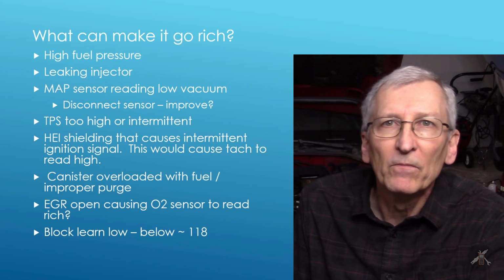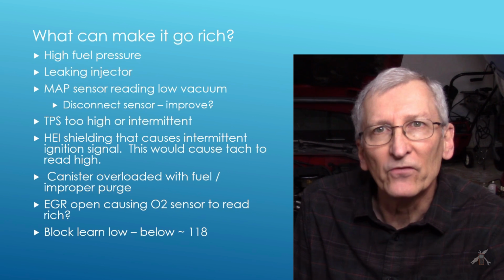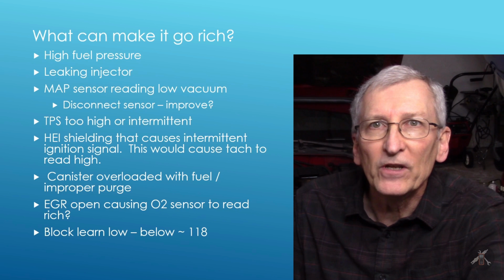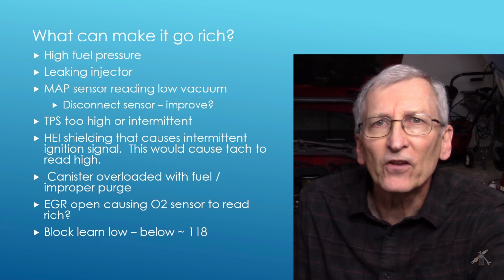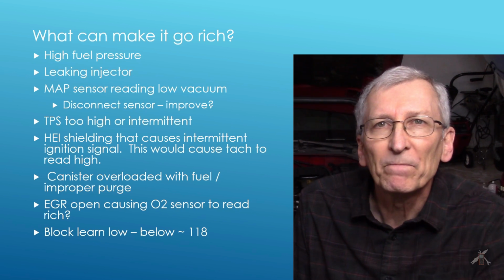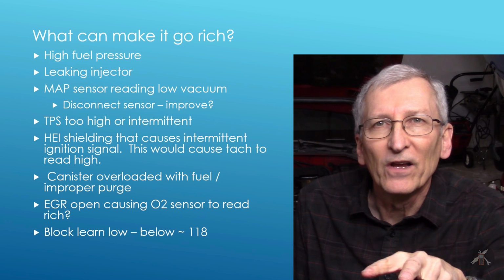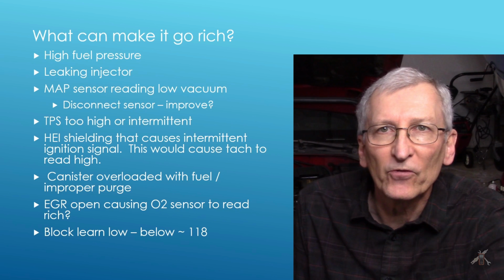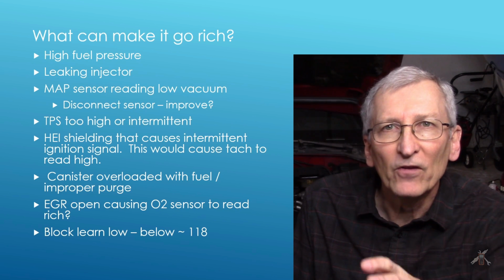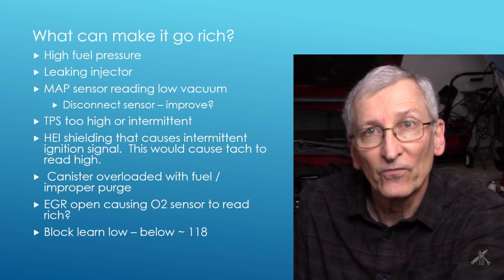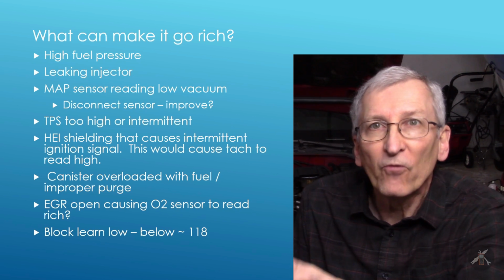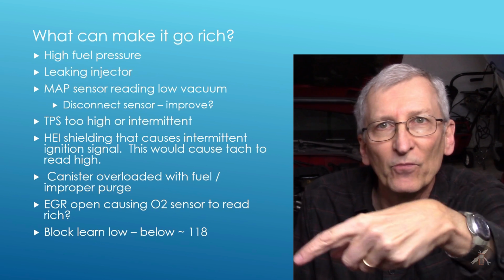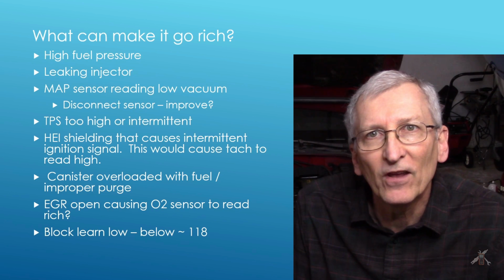If you happen to have a throttle body engine, well then, if it's a V8 or a V6, typically it'll be a dual bore. And each one will feed half the cylinders. And if you look at the manifold runners, if it was a V8, you'll see, if say one injector's running really rich, 4 cylinders ought to be coloring the plugs different than the other 4. And you should be able to tell based on the pattern in the intake manifold.